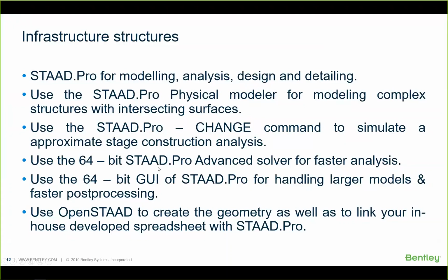And use the 64-bit STAAD.Pro advanced solver for faster analysis. Use the 64-bit graphical user interface of STAAD.Pro for handling larger models and faster processing. In the latest version of STAAD.Pro, the number of nodes doubled to nearly 450,000 nodes compared to the previous version, which was handling only 225,000 nodes. And use the OpenSTAAD feature to create the geometry as well as to link your in-house developed spreadsheet with STAAD.Pro by writing macros using Visual Basic for Applications and using the OpenSTAAD routines in those macros.